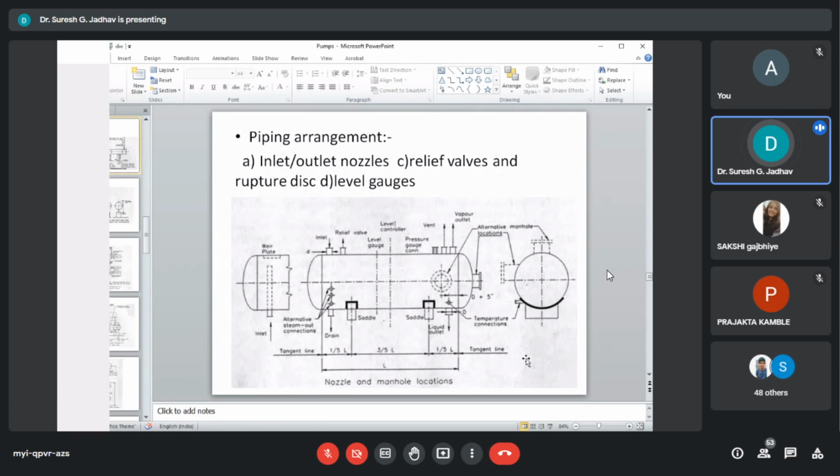Pipe racks shall be arranged which will support electric and instrument trays along with pipelines. Piping should not transmit vibration and should be isolated from vibrating equipment with the help of expansion bellows or hose. Such equipment are centrifuges and filters. Now let's see supports.